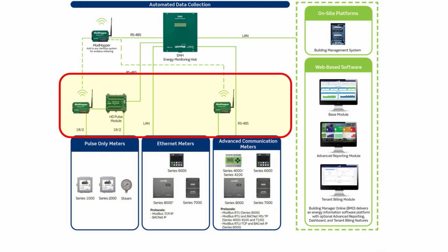Getting the data out of the meters to an analytics platform may require the use of some intermediate communication devices. Pulse meters typically require some sort of pulse counting interface to convert their pulse output to usable data. In some instances, running wiring between devices in a system may not be feasible, so a wireless transceiver may be utilized in place of hardwired connections.